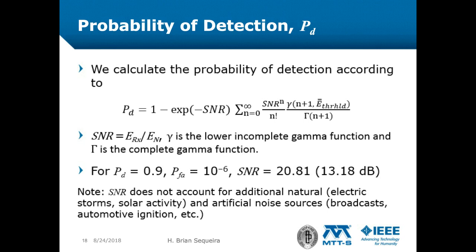It is interesting to note that the detection criteria is satisfied solely by energy ratios. Apart from the assumption that the noise distribution is Gaussian, nothing is yet known about the signal or noise individually. This indicates that a rich variety of signal pedigrees can accomplish detection performance as long as its energy and accompanying threshold satisfy prescribed ratios to noise energy.